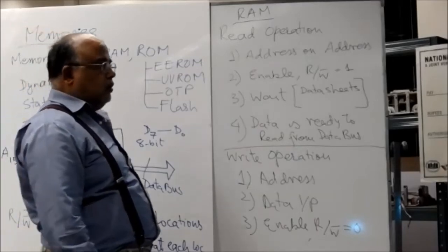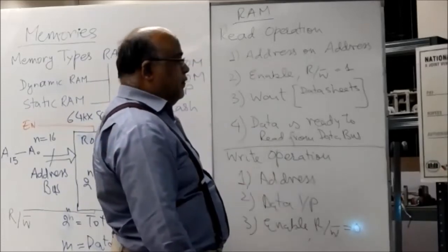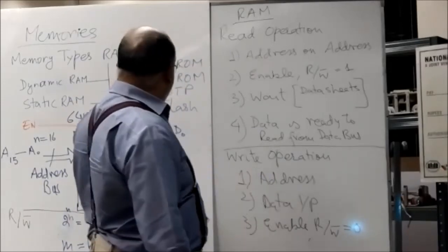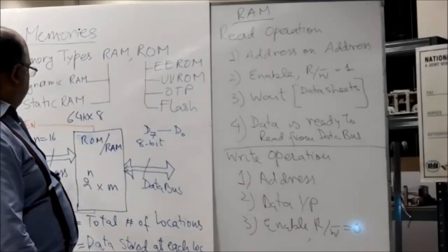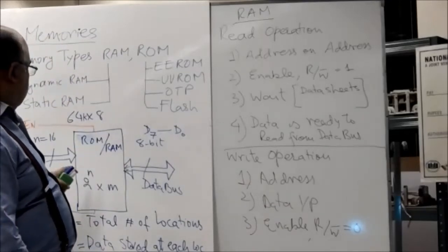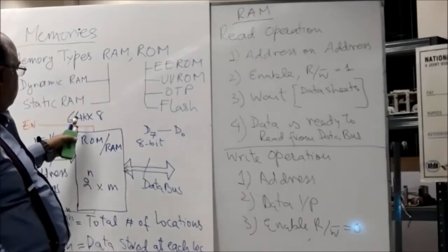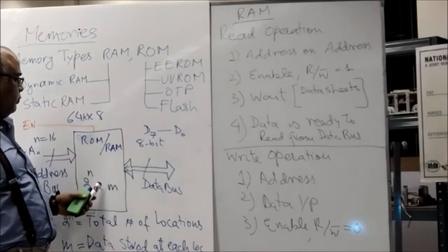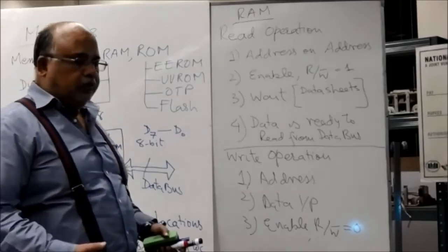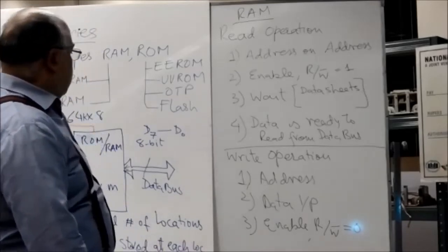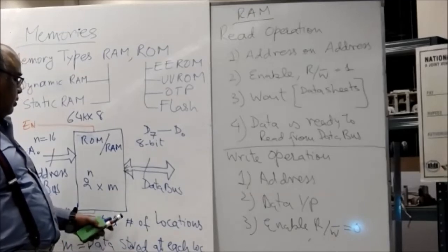So the processor does that in steps. Address is given first because it takes a long time to find out which location is to be written to. So basically, address is the pointer which points to hundreds of 65,000 locations in this memory. So the bigger the memory, the bigger the address bus, and the bigger the number of locations.